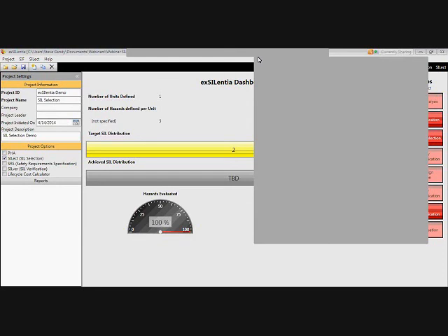And there's a question that's come in that has 3 parts. I will probably have to answer that question because it's quite detailed. For example, what should be done if it's classified as a SIL based on a risk graph? Risk graphs, and I said, as long as you're consistent in the technique you're using and you're conservative, you shouldn't have too many problems. The important thing is to make sure that you do err on the side of caution.